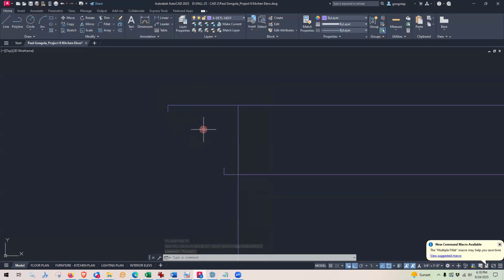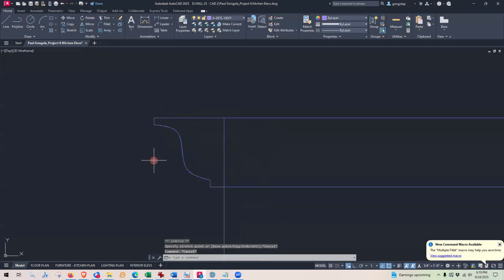All right, so now I'm going to do the curved face or the curved edge of that crown molding. That S-shaped curve is called an ogee, O-G-E-E. I am going to draw that, and I'm just going to use my spline fit to do that. So I'm going to come here. Let me turn my ortho off. No, that's not too bad, actually. If I wanted to play with this, I could pull these down. But you know what? I think that's going to be just fine.